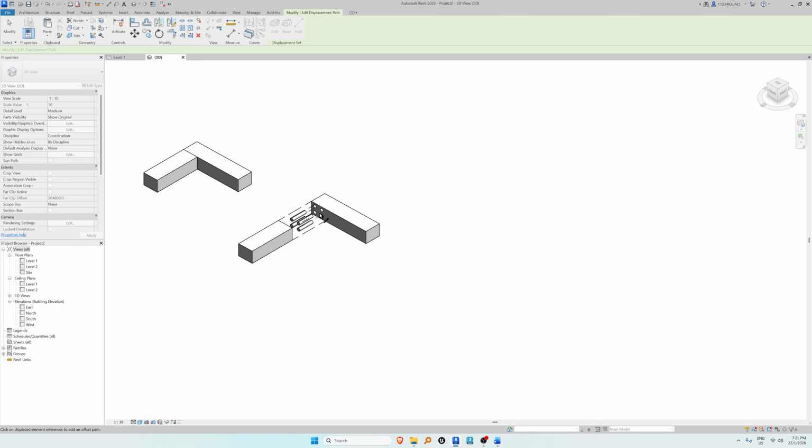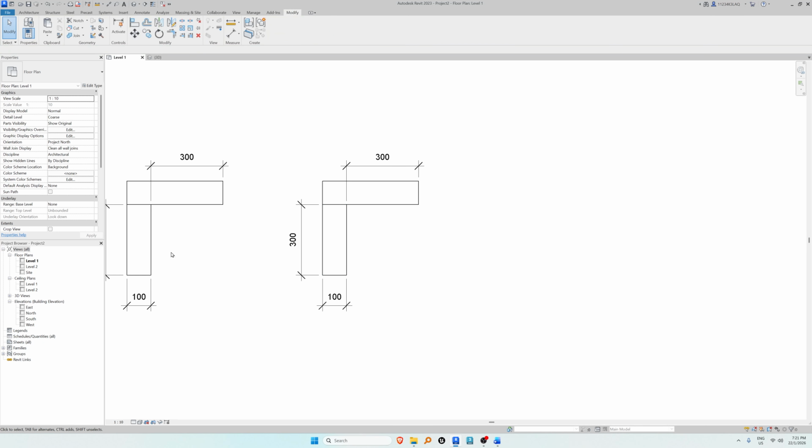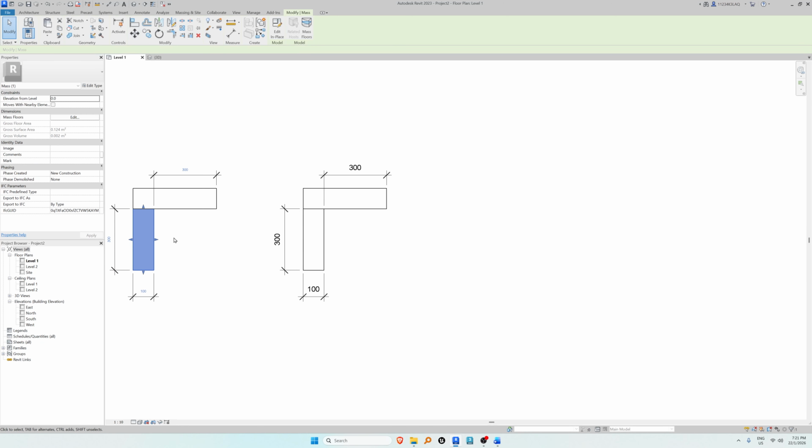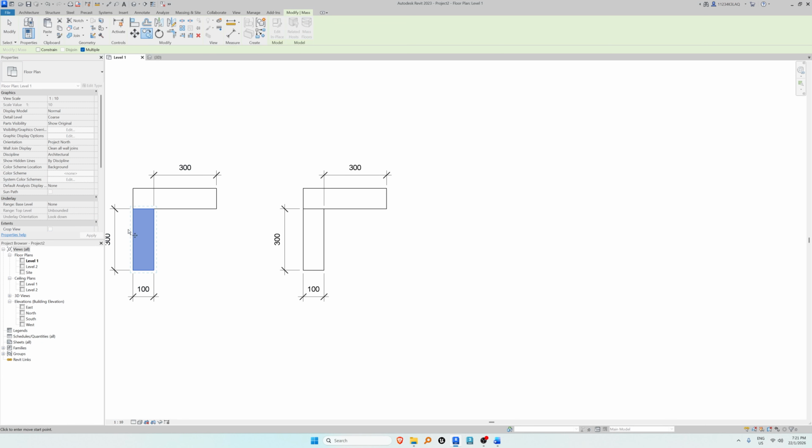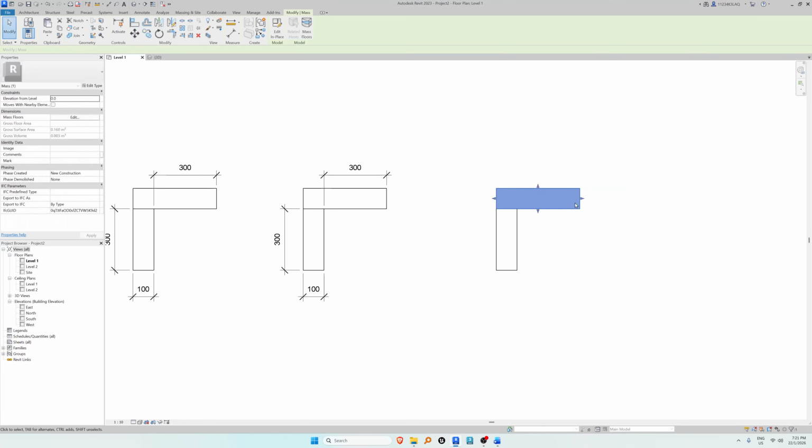Let's make another joint perhaps. Let's make a dovetail. Okay, go on top here. Pick this one. Let's make a copy first. Okay, you can use this tool, CO, copy, or Control C, Control V. This one allows you to pick where you want to start copy from. So you can use that one. And then I'm gonna pick this, copy, CO. Let's place it here. This one I want to make it shorter this time. I can always align the sides.